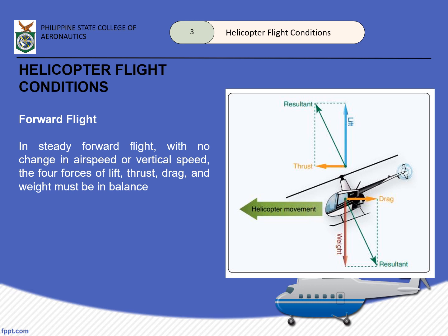Because the rotor blades turn in a circular pattern, the velocity of airflow across the blade depends on the position of the blade in the plane of rotation at a given instant, so its rotational velocity and the airspeed of the helicopter. Meaning, the airflow that comes in contact with our blades, they vary. They tend to vary.